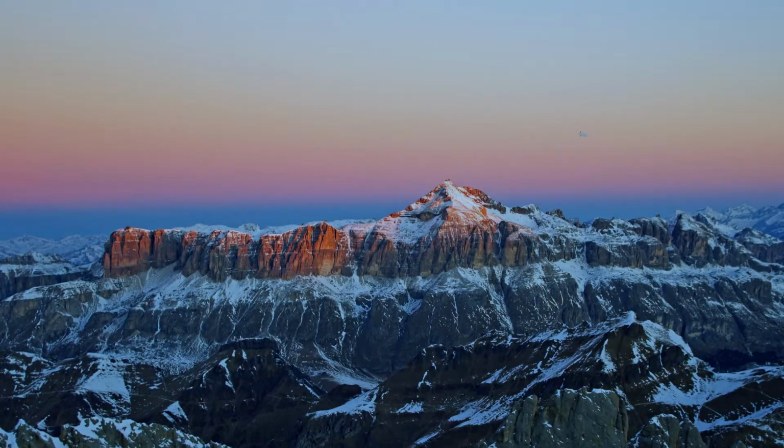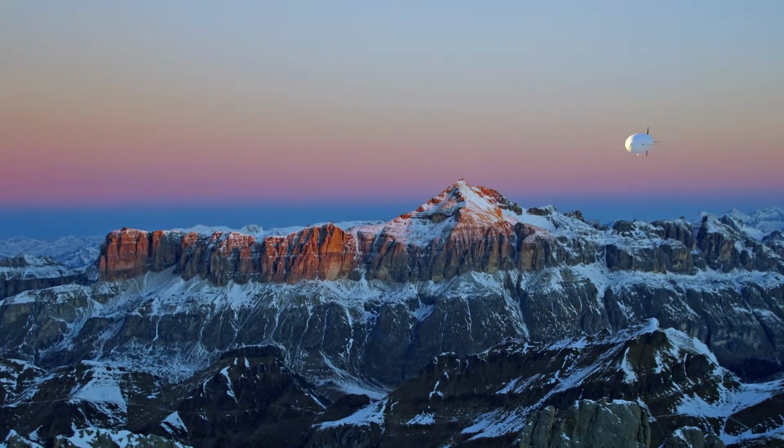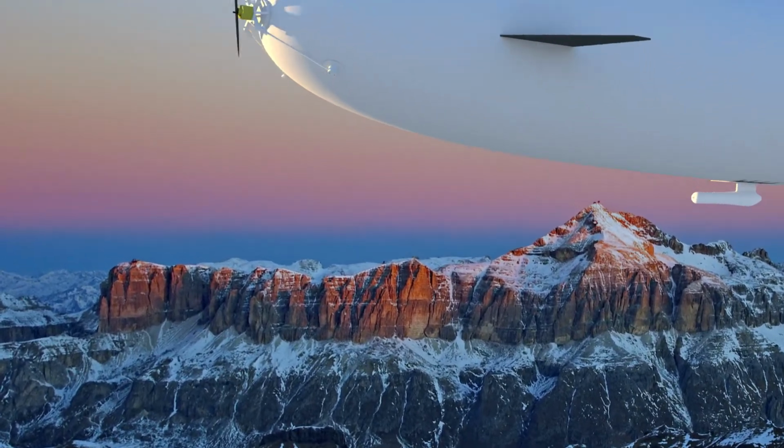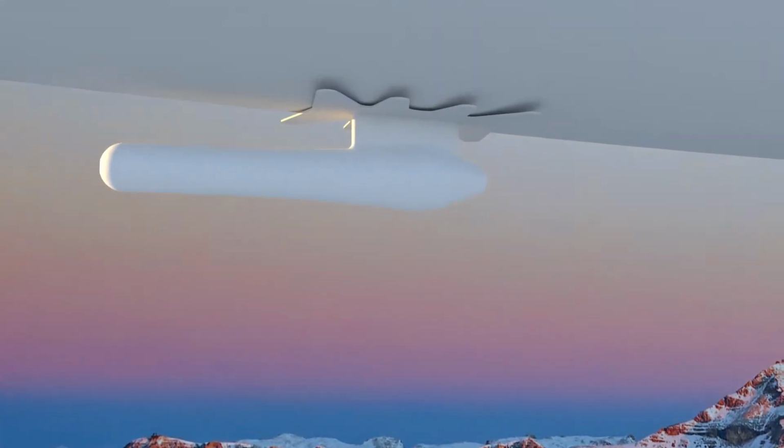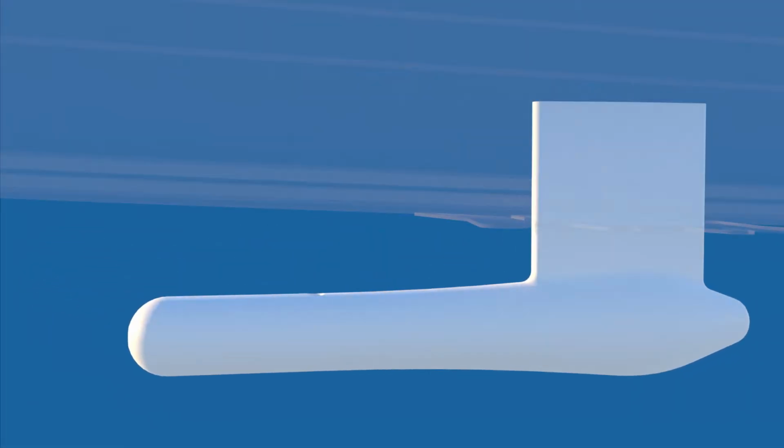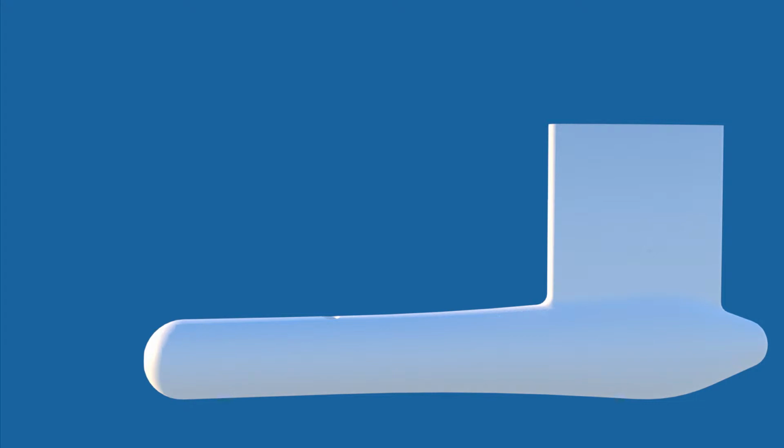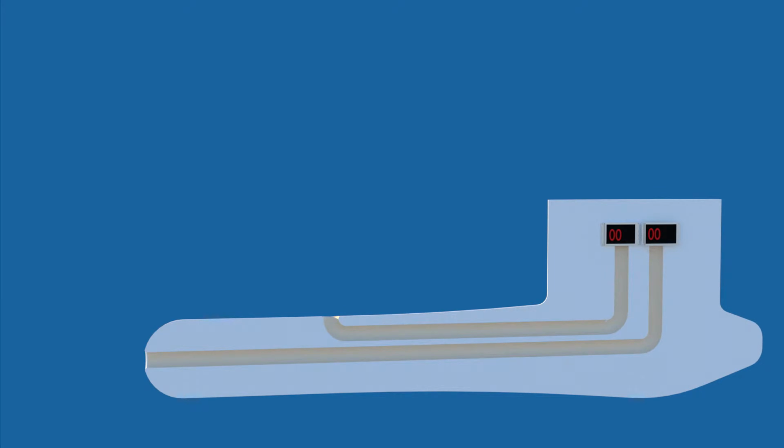Bernoulli's equation in the case of incompressible fluids can be applied to gases. Gases are compressible fluids in general, but there are situations in which the density of a gas does not change, for example in the case of a pitot tube, a device used to measure velocities. In this example, we want to measure the velocity of a zeppelin.